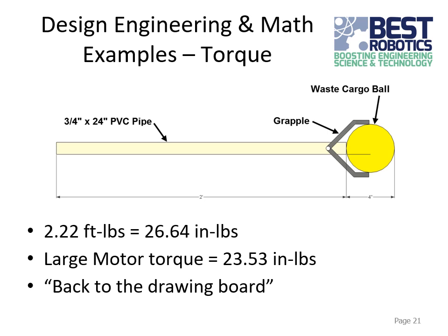And I would add to that, even if the required torque ended up being just below that motor torque, you really want some margin in there too, because if they're basically the same, then it's just going to stall there, and it's not going to lift it very quickly, or it would be really slow.